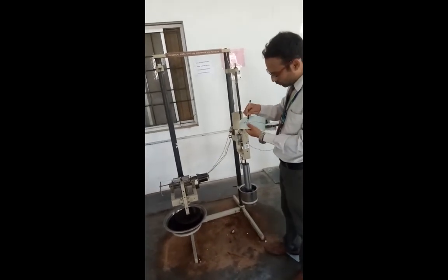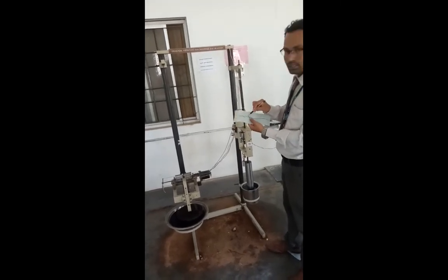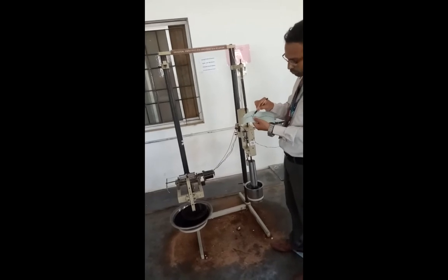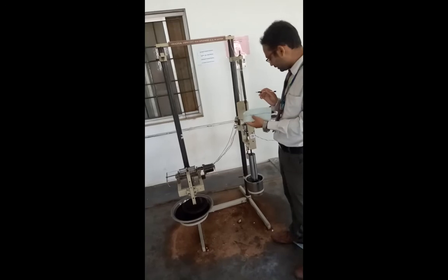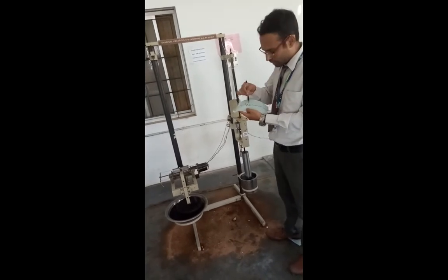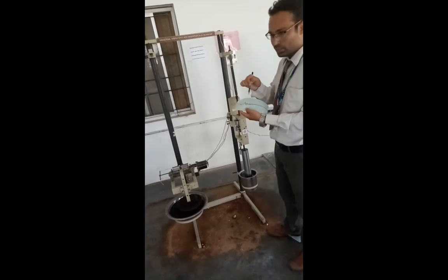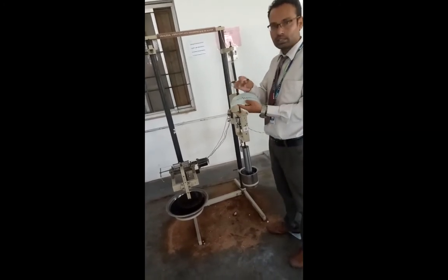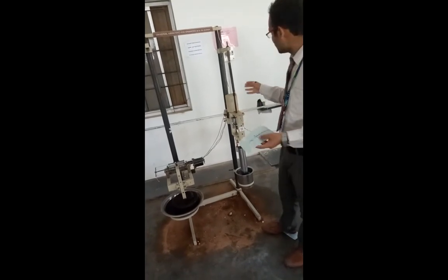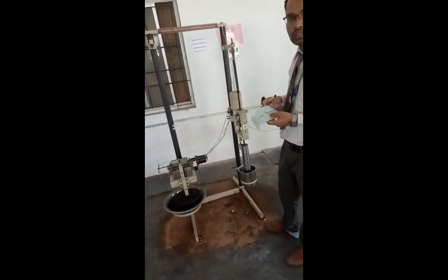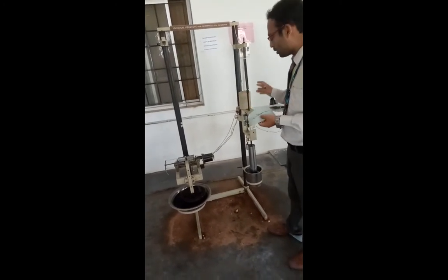Finally the logarithmic decrement goes on decreasing. From the mean position to the top is called the amplitude. Similarly the amplitude goes on decreasing, and finally you get zero. From the graph you take the value of one cycle, that is xt, the top one x1 and the bottom x2. Use these values for the calculation, and finally you get the logarithmic decrement and time period. This is the damped longitudinal vibration with oil. I hope you understand how to take the reading.